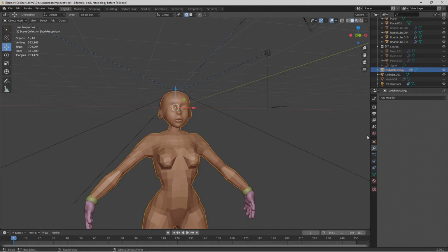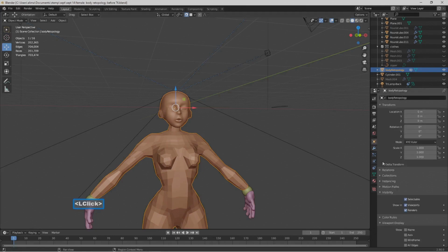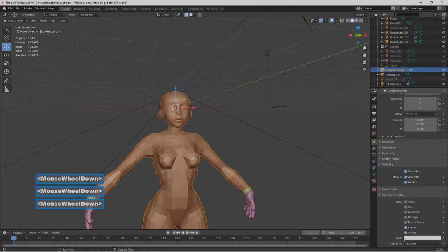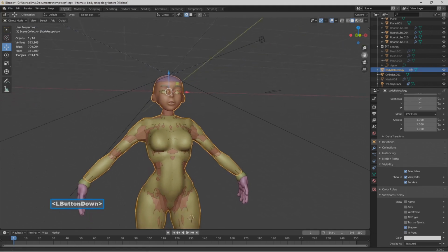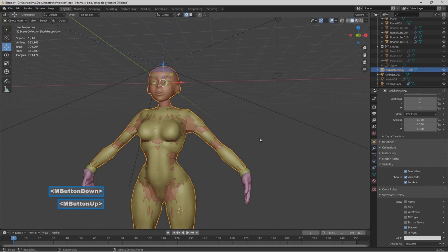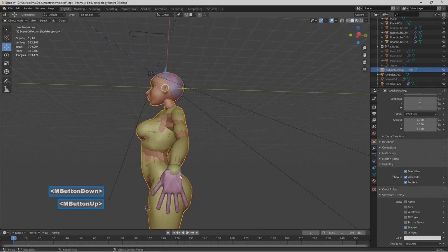Okay, what we're going to do now is go to the right side of the screen to what looks like the square. We're going to select in front to take off the ability of our retopology to show through everything. I'm going to select the hand to pan up. I'm going to turn off snapping by going to the upper center of the screen. I'm going to hold the middle mouse button to go towards the side of the screen. I'm going to hold, not control, hold shift, then right click to put the 3D cursor right here.